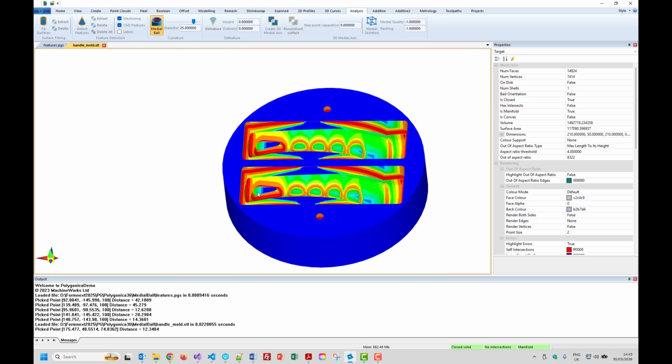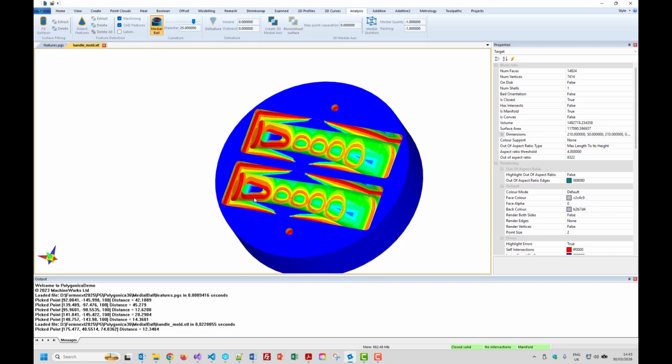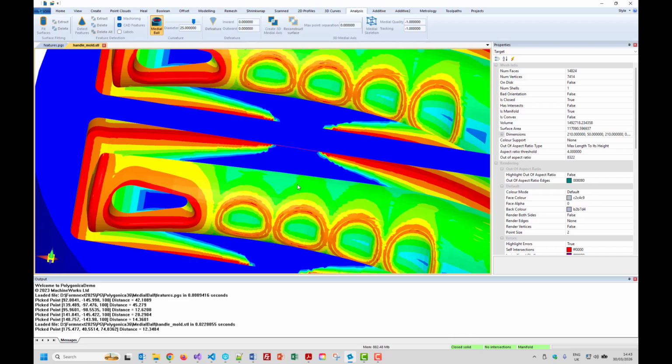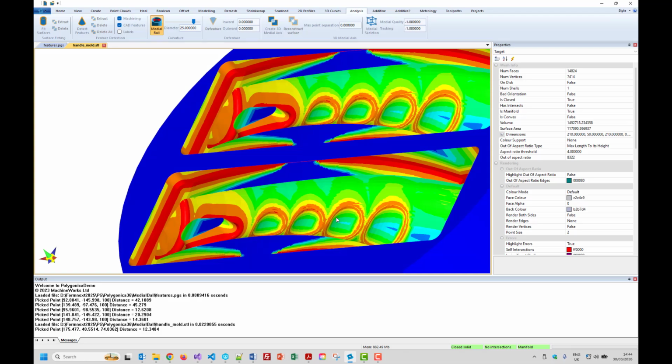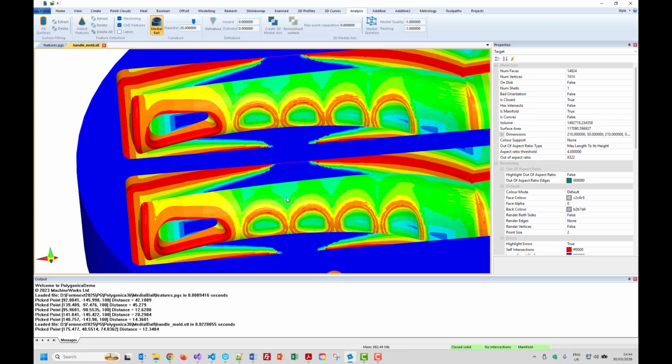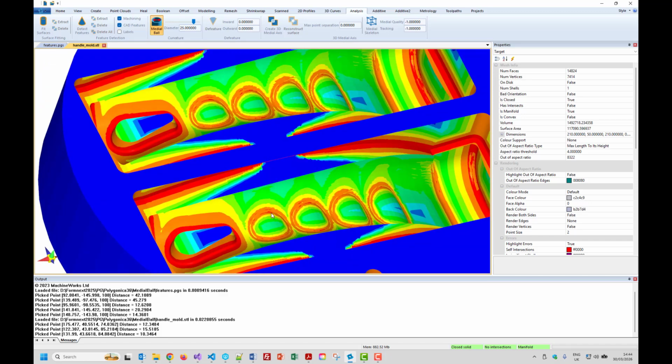But if we double click here, you can't reach this bit because actually you'd need something around 12 to get into there. So it's a very quick way of visualizing the curvature of the part and the types of tool radiuses you might need. And again, along here you can see this wavy pattern. That's because we've got these islands protruding up. So if I click here in between the islands, I'm going to be able to fit a bigger sphere, 15, than I can at an equivalent point here where it's 10. So again, it's taking into account this local accessibility.